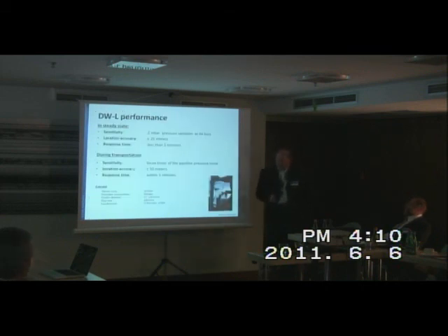By our experience, we can observe a pressure variation of 2 millibars on the pipelines in steady state when the transportation is stopped. During the transportation, the pressure variation that we can observe must be three times greater than the pipeline pressure noise, because in every pipeline, for mechanical and electronic reasons, there is a pressure noise present, also in steady state during transportation. It means, for example, if the pipeline has a noise value of 10 millibars, we can observe a pressure drop of 30 millibars.